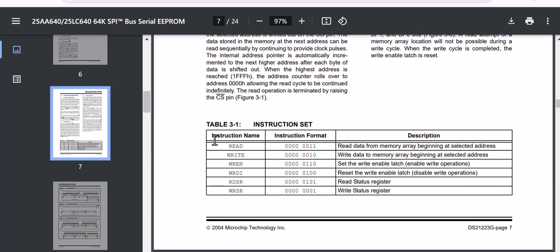To control this SPI chip, there are certain instructions we need to send before a write or read. Mainly, 3 means the read instruction, 2 means the write instruction, and 6 means set the write enable latch. There are also certain areas we can protect as well.